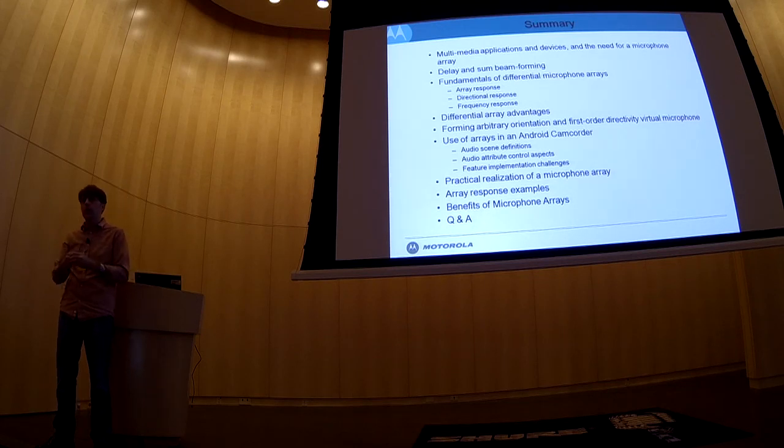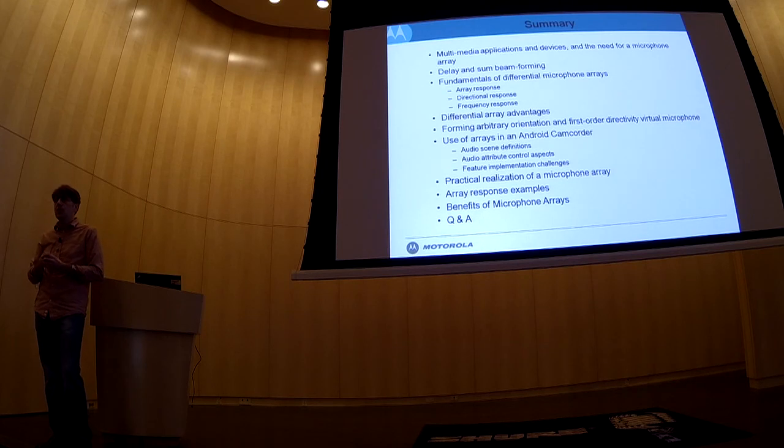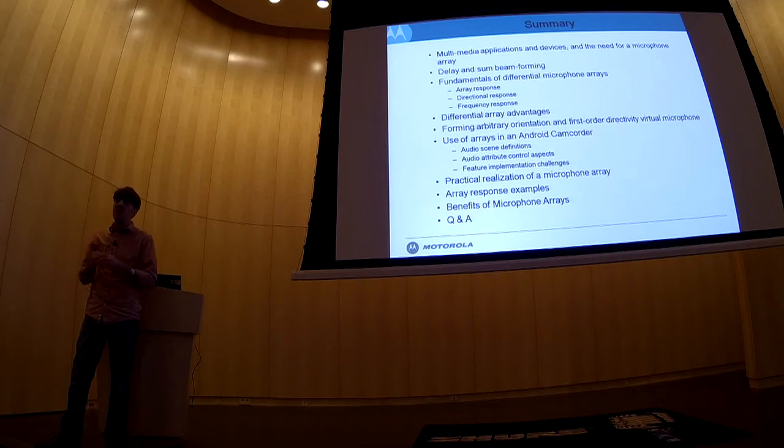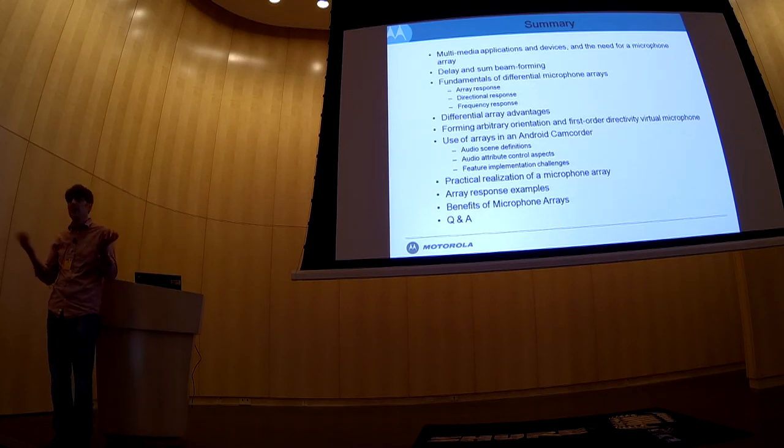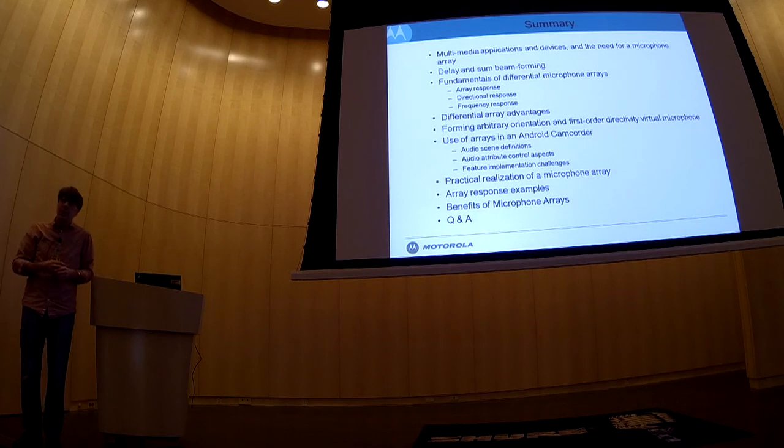But that's not the only way to be done. There's various... Selects the lesser evil, right. And given the fact that the acoustic signal is somewhat similar, coherent across multiple mics, but the wind noise is not, by that minimization, and the wind noise is quite a bit higher than the rest of it usually, that sort of minimization can work. And there's various other implementations. And like I say, that's not very cheap computationally to do, however.